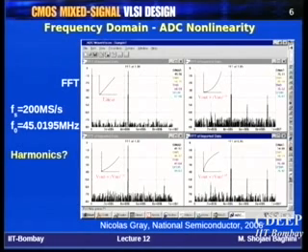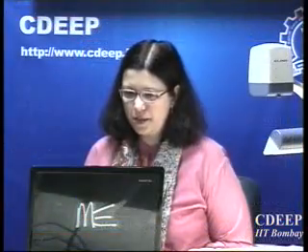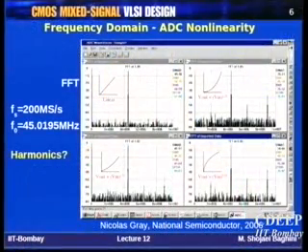For example, you can just run FFT and then for your signal, instead of V in, you can use a sine wave, and run FFT on a sine wave, say to the power 1.05. And then you will see similar results. Because after all, MATLAB also samples the signal and gives you the FFT components. And then eventually this level, like here for the ideal case, is minus 70 dB. This is called noise floor.